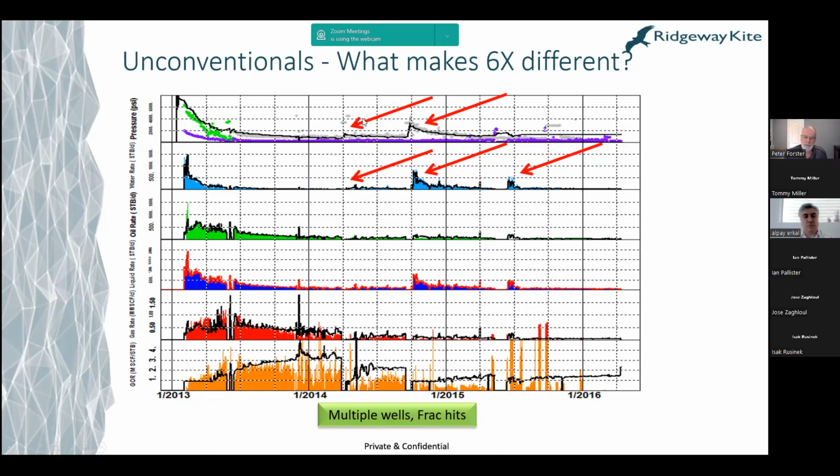These little gray blobs here, which hopefully you can see, are historical observations. So this model has been history matched to reasonably match the behavior of the actual well, so that we can reproduce the real world behavior in our calibrated history matched model.